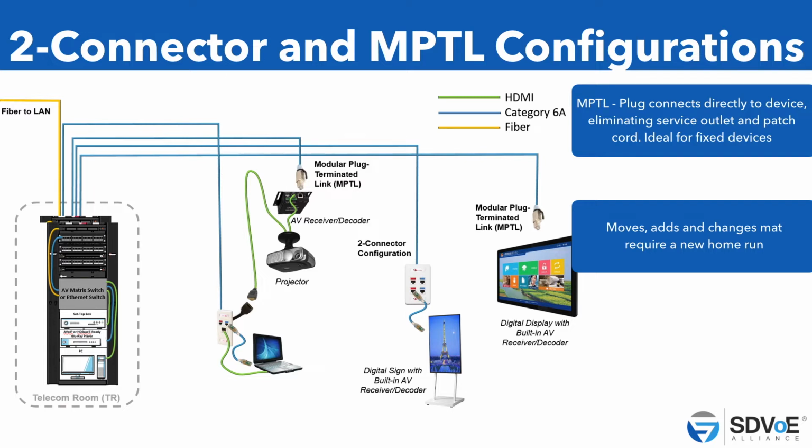Now there's another thing. How many of you who are installing traditional AV cable are using something like coaxial? Anybody still using coaxial? No? Anybody using any other type of cable? But do you know if that cable is CPR compliant? Has anybody heard of CPR compliance? No? So CPR compliance is all about the fire safety rating of buildings, and that your cables have to meet a certain fire class.